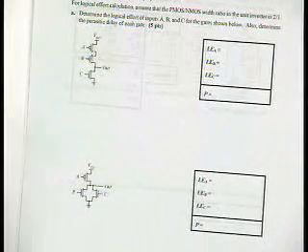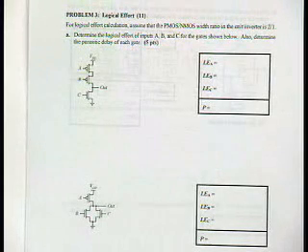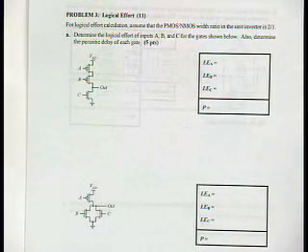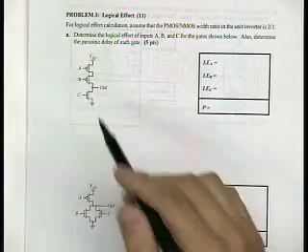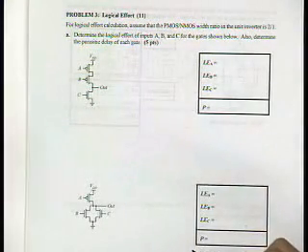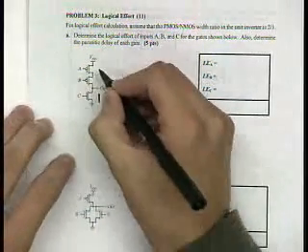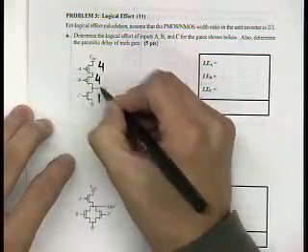So now the logical effort. We gave you first a warm-up example, simple and straightforward, to just figure out if you understand the very concept of logical effort. You had to determine logical effort and parasitic delay for these two simple circuits. So what you need to do is simply balance pull up and pull down resistance to that of a unit inverter. So this is 1, then this is 4, this is 4.